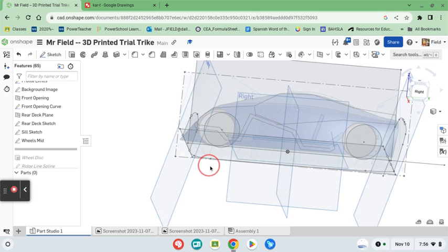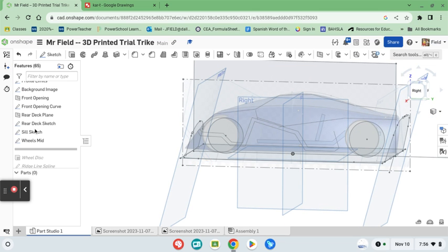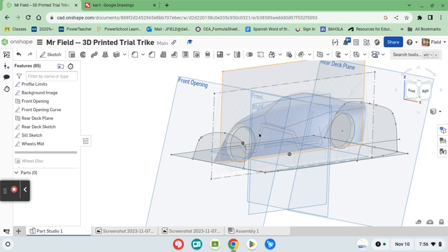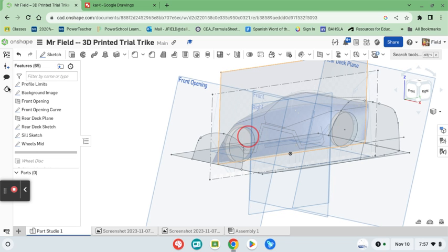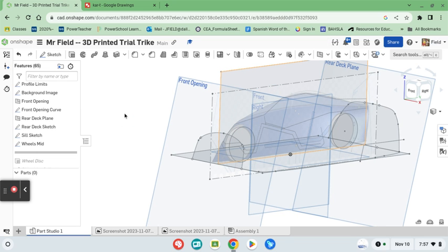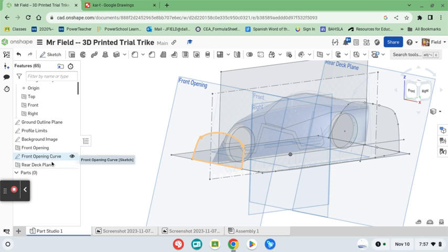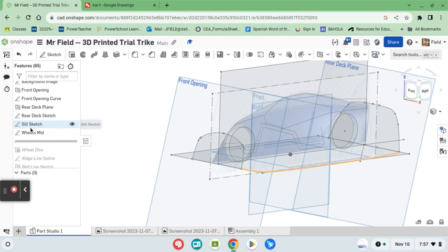And then I wanted to create wheels. So one of the things I did was create those sketches of the wheels on the right plane. So you can kind of see it underneath, or I get in the habit of just picking the right plane up here from the left menu. So you see it highlighted right there. And I put in the 2 center point circles for my wheels just to get them in there. And you can do the same thing if you wish right here.